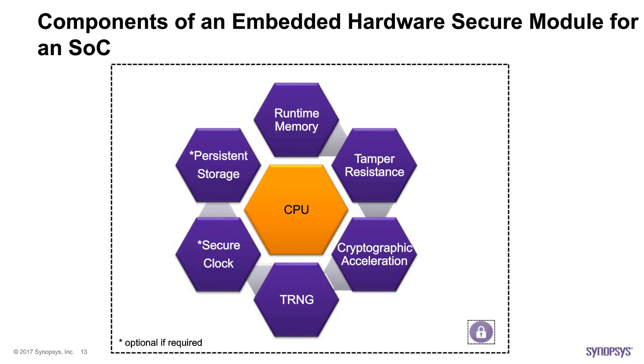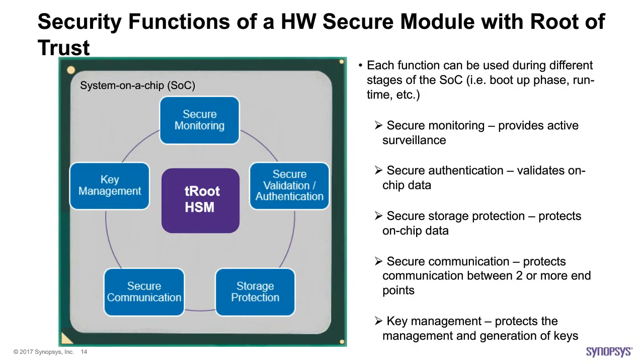So here are some of the main security functions provided by a hardware secure module. Secure monitoring. This feature can be available during power-up and during the runtime operation of the SoC. It will ensure that the proper components of the SoC are functioning properly. For example, it can monitor host instruction code while the host CPU is executing it. An attacker trying to insert malicious instructions can be detected, and this can cause a notification back to the SoC.